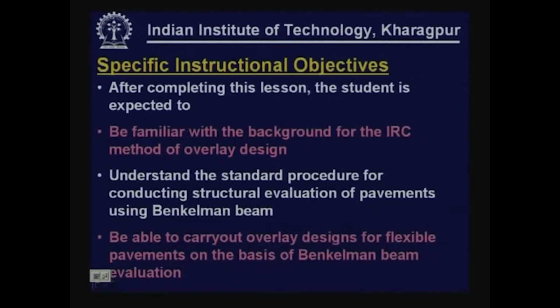It is also expected that the student would understand the standard procedure to be adopted for conducting structural evaluation of pavements using Benkelman beam, because IRC 81 1997 version is based on the structural evaluation of pavements using the Benkelman beam evaluation technique. It is also expected that students would be able to carry out overlay designs for flexible pavements on the basis of Benkelman beam evaluation.